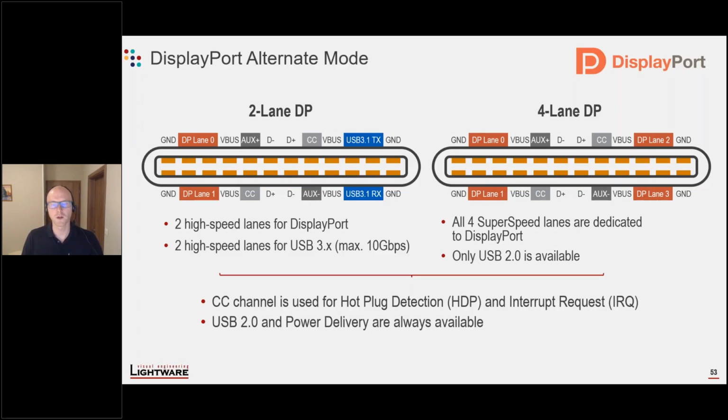Now, an interesting feature of DisplayPort is that it can use one lane if the required bandwidth is low enough, or it can choose to use 2 lanes or all 4 lanes. The rule of thumb is that it tries to use the lowest number of lanes at the highest possible speed to minimize power consumption and minimize electromagnetic interference.